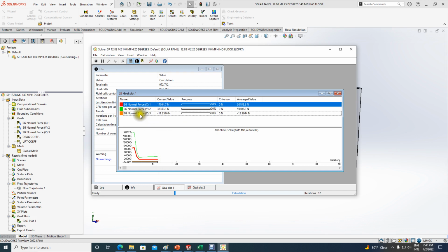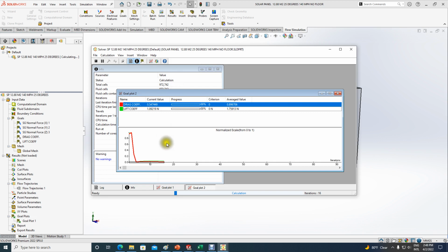On the Z coordinate, pretty much nothing is happening, as expected. So let's see, this is still high, 1.11. If these numbers start to change, way too high, maybe that will prompt me to include a finer mesh, to increase the mesh size, perhaps in the Y direction as well, just to have better results. But they are ballpark. They are still holding.